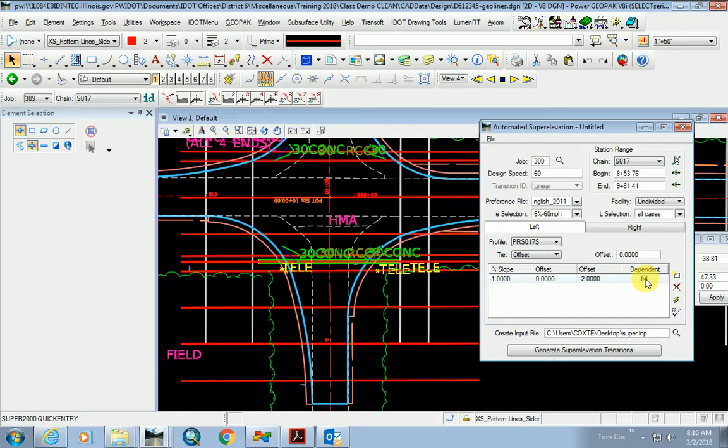And sometimes I'll give you an example of an independent shape. If you had a mainline pavement where you've got the mainline lanes, but then you're also adding a turn lane. So let's say the mainline through lanes are 1.5% and your turn lane is 2%. So in that case, you would place a 12-foot wide shape at 1.5%, and then you would add in here, you can have multiple shapes. So you'd have a shape right adjacent to the other one, and that shape you would have to say the turn lane shape. That's an independent shape because it's independent of the profile.